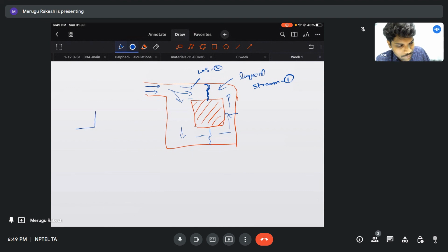So if you see hubs like this, now the fluid enters in this way and the fluid enters in this way. Somewhere you will get the crack appearance. This is called the cold shut defect. It does not have enough heat content in it to freeze and form a seamless casting. So this appearance of the crack is known as cold shut.